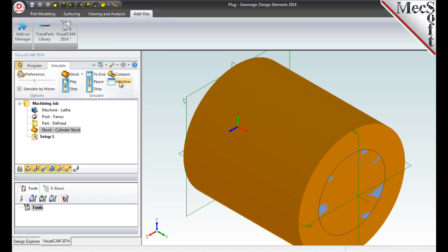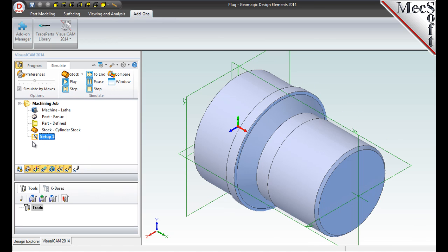Now, let's discuss the machining setup. The setup icon displayed in the job tree defines the Turn Machine Coordinate System, or MCS, and is defined automatically. CNC turning centers, or lathes, use the Cartesian coordinate system for programmed coordinates. They follow the convention that the spindle axis of rotation is designated as the z-axis. Secondly, the axis perpendicular to this axis, along which the tool travels to cut into the stock, is designated as the x-axis. So, the part and spindle rotate about the z-axis, and moving the tool along the z-axis provides the direction of feed, and moving it along the x-axis provides the depth of cut.